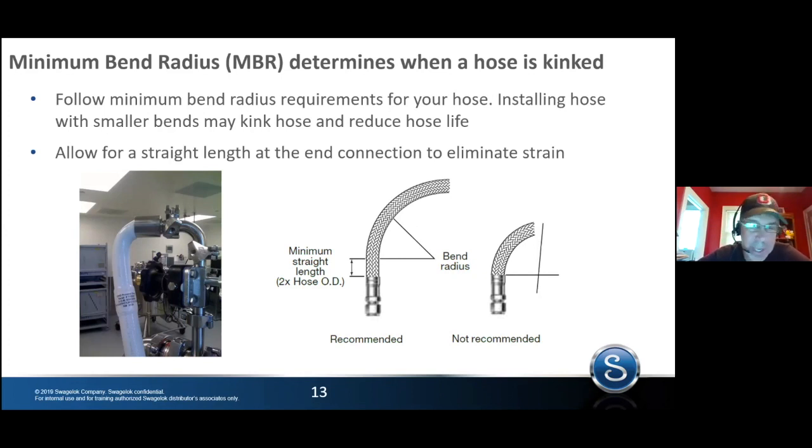How often is it cycled? How often does it move? How often is it used? And you track the install date and the failure date. And that's the best way to start getting that data. But the first key in all that is cataloging. Yeah, every hose has to have a name, and every hose needs to be down on a sheet so that you know when it was born and when it died.